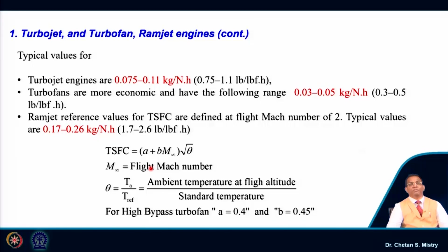Now, for the ramjet engine, this number will be on the higher side. Ramjet engines have a specific fuel consumption in the range of 0.17 to 0.26. You must realize the applications of these engines. Where I am using the engine will decide my thrust specific fuel consumption.